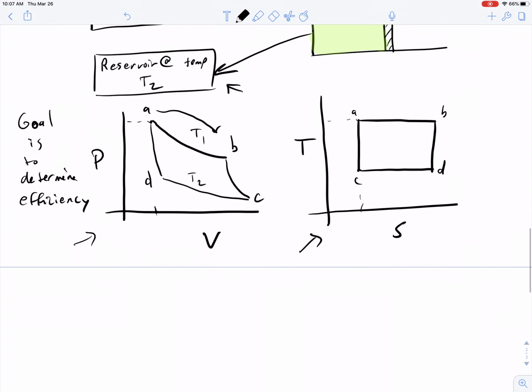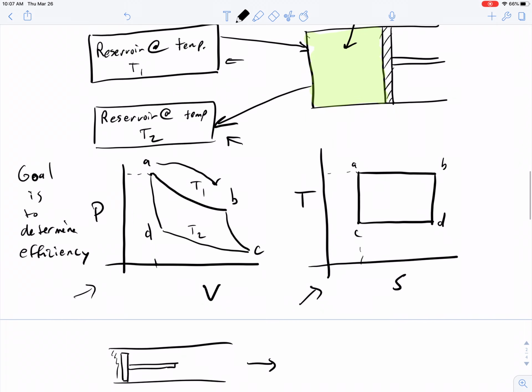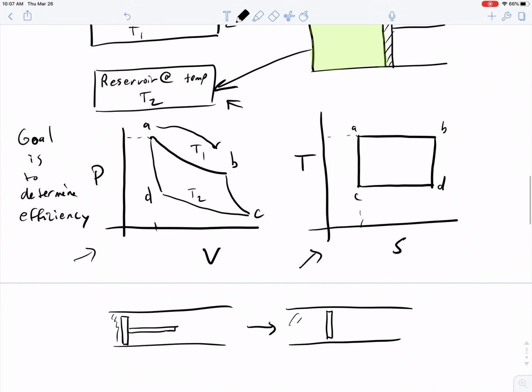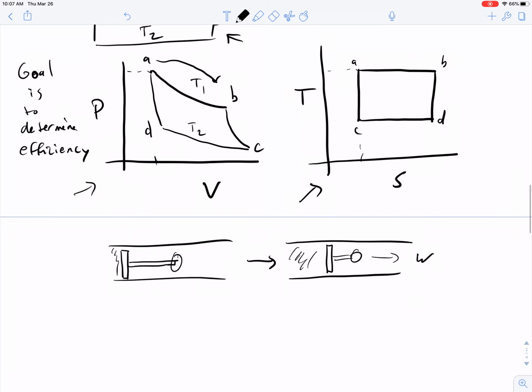Starting with the lowest volume and the highest pressure, our piston will be in the phase where it's here, and the working fluid is right here. What's happening is it's going from that space over to a situation where the working fluid volume is going to be substantially larger with a pressure that is lower. So we're going to go from that to that. And by having some device that attaches to the connecting rod of your piston, you're able to extract work from that process of expansion as you go around the entire circuit.